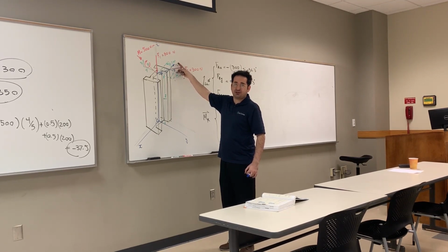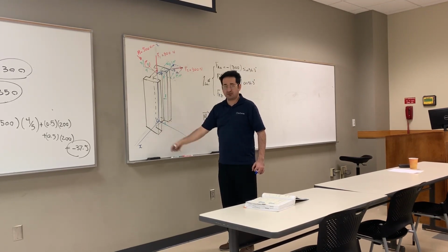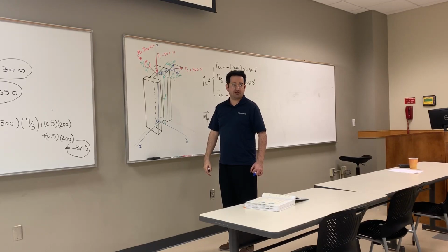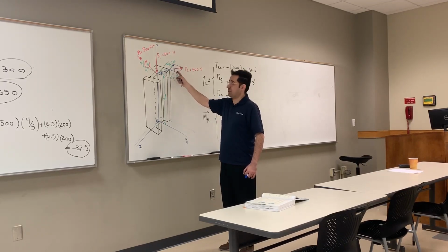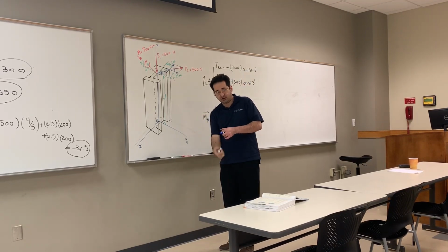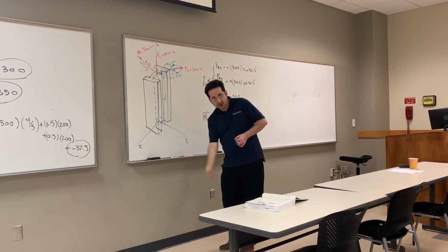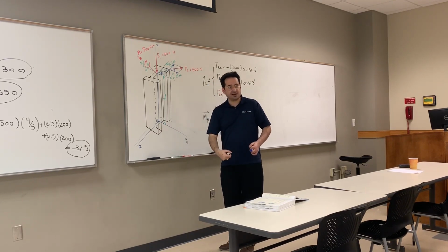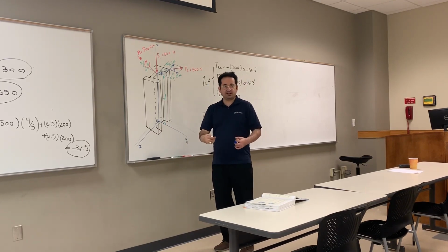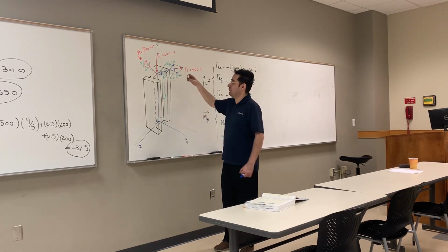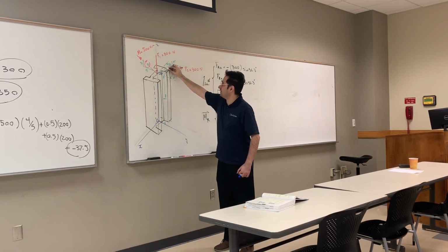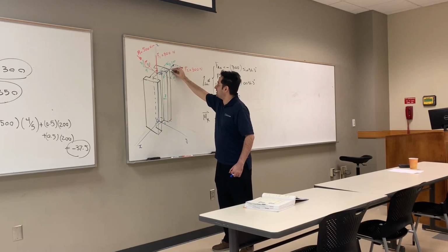Then you ask the question, can it generate a rotation about the x-axis? It's parallel, right? So you ignore it and go to the next one. What about this one? Again, you ask, can it generate any rotational effect, a torque, about the x-axis? Yes, then you compute it. Then you go to step 2, move it. Where should I move it? Back, here.